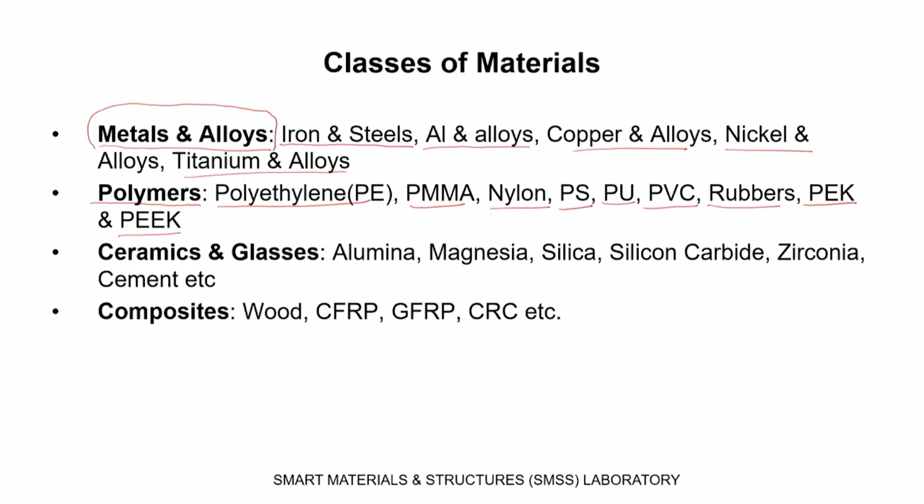And polymethyl methacrylate, let us take this one, it is also known as perspex. It has a very wide utilization. For example, we choose PMMA for dental fixtures. We also choose polymethyl methacrylate, perspex, for different types of transparent system development. Polyvinyl chloride, you know it very well, is used for pipes, and that is something which can take many different shapes. By using certain plasticizers, you can give it different shapes. So, this is a powerful material. So, considering all these things together is our group of polymers.